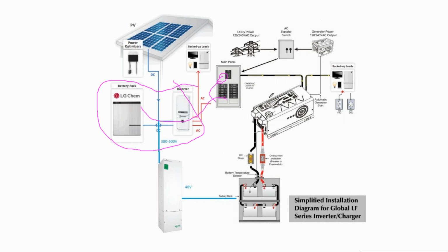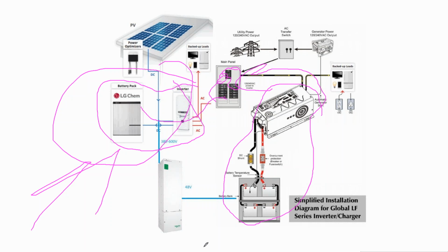And so actually, you could put a generator interlock panel here and then use your battery inverter to power the house, and then just reprogram your lithium-ion battery to do demand management so that you reduce the spiky loads from your battery bank.